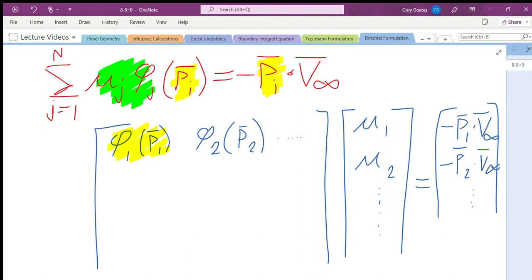That's the really fascinating thing about this: just by reformulating the equations, you'll notice that your outputs are almost exactly the same. It's going to be basically in the numerical noise that you notice any difference between the Dirichlet and the Neumann formulation. But just because we've reworked it a little bit and approached it from a different angle, the Dirichlet formulation is well posed, whereas the Neumann formulation is not. And so we get a good solution out of the Dirichlet formulation without having to use least squares or anything like that. Okay, pretty remarkable.